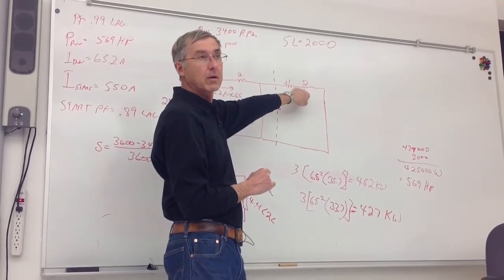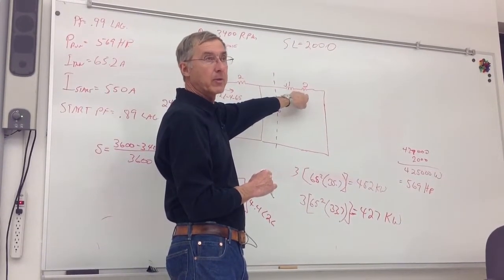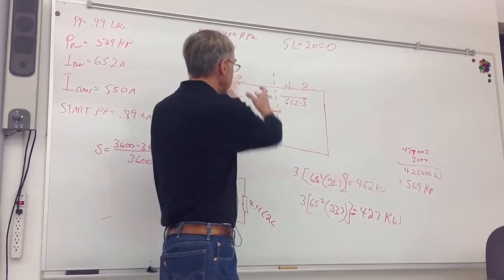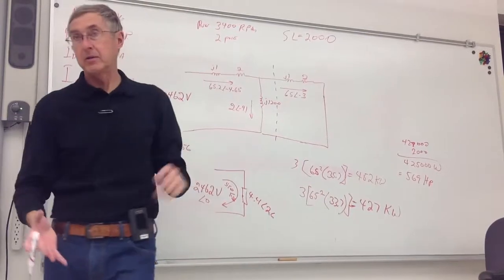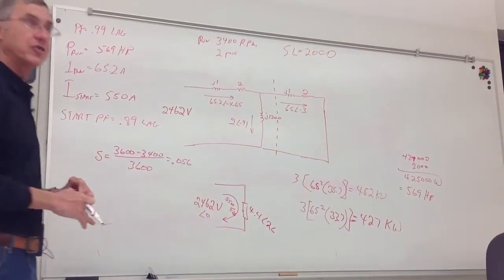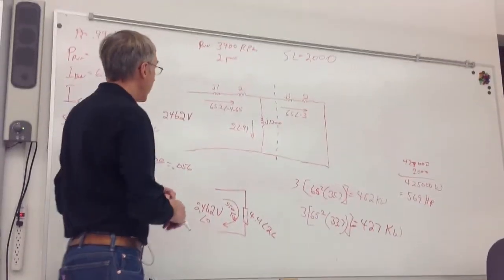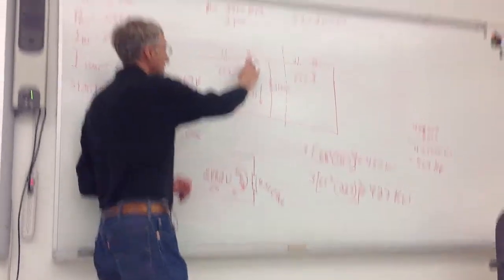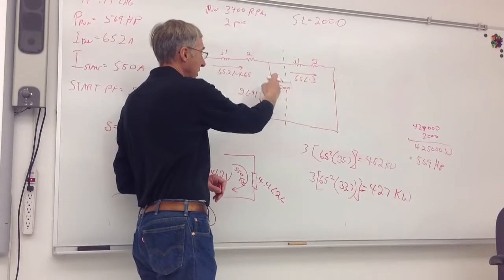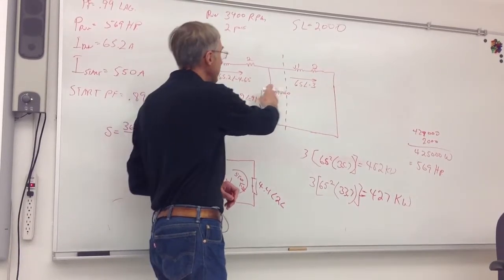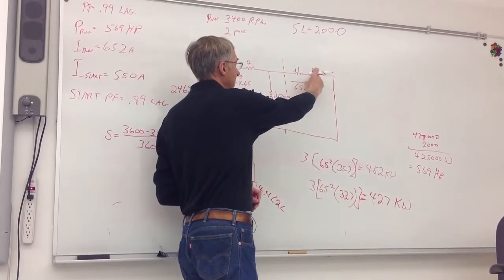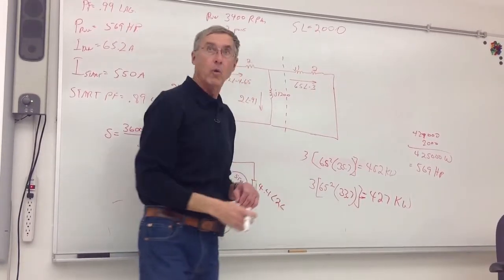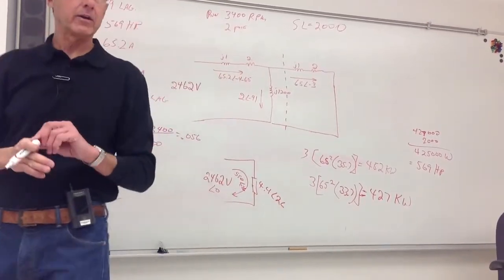The copper losses in the rotor. So all these things are losses of some kind, using either watts or vars. And I'm picturing the stator var loss, the stator real power loss, the magnetization var loss, the rotor var loss, and the rotor copper loss, as one way of thinking of what those things are.